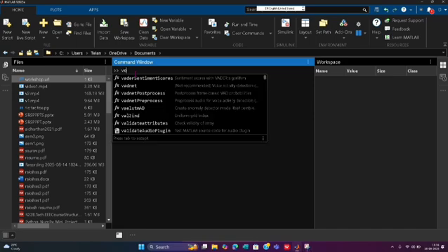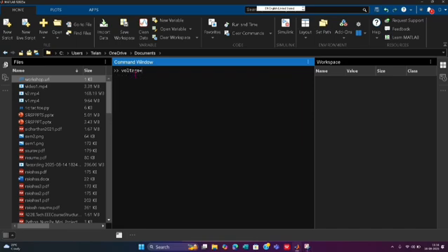I'm creating a variable voltage and assigning it the value of 230. As we can see here, in the command window, it is displaying voltage equals 230, and this value is stored in the workspace with the name voltage and value 230, and its size is shown as 1 cross 1, which denotes that it is a scalar quantity, and in MATLAB by default its class is defined to be double,